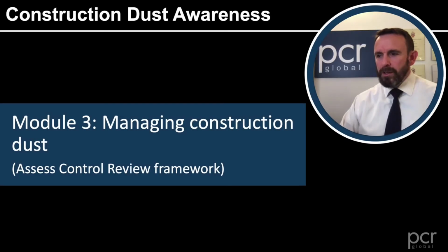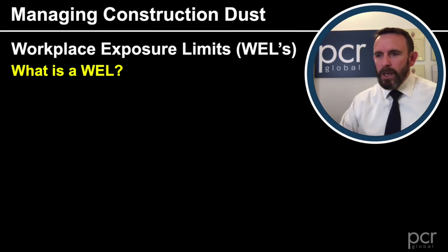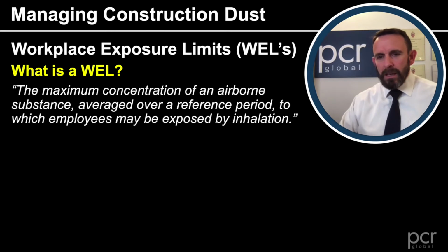Module 3, managing construction dust, following the assess, control and review framework from the HSE. Workplace exposure limits, WELs. What is a WEL? A WEL is the maximum concentration of an airborne substance averaged over a reference period to which employees may be exposed by inhalation.